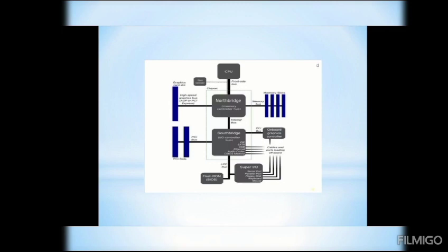This is a diagrammatic representation of a chipset. The north bridge typically handles communication among the CPU, RAM, AGP or PCI Express, and the south bridge. Some north bridges also contain an integrated video controller, also known as a graphics and memory controller hub in Intel systems. The south bridge is a chip that implements the slower capabilities of a motherboard because the south bridge is further removed from the CPU. It is responsible for the lower speed devices on the typical microcomputer.